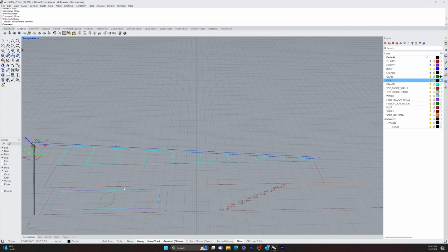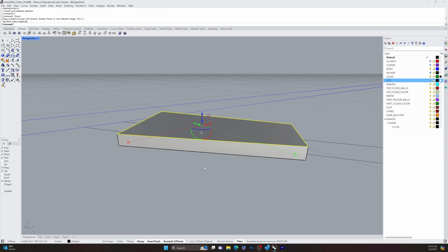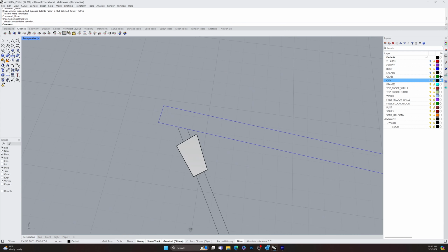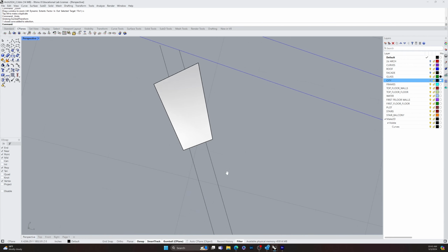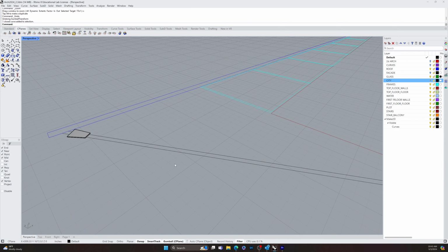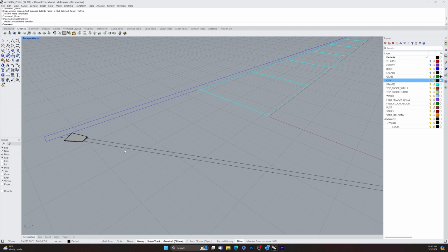And let's go ahead and extrude this out. Okay. Let's see. Z, enter, S, enter to zoom on the selected. And I'm going to pull this out. Let's do 2 inches. No, too much. 1 inch. Yeah, that's better. And I'm going to keep this geometry flat because it does make things have lower polygon counts when we start getting into real-time rendering and stuff. We want to keep our polygon count low, so I'm not going to do an organic shape here.